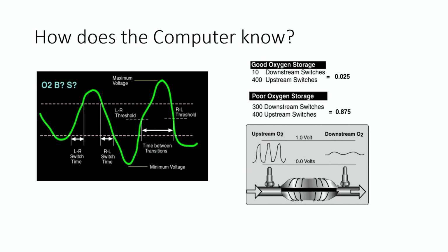But anytime we're dealing with an oxygen sensor waveform, and again, you could always go to generic OBD2 to see actual O2 sensor voltages. I know a lot of times we're dealing with lean air fuel ratio sensors now, if we were on the factory side using our scan tool. But on the screen you guys see a typical oxygen sensor waveform switching from rich to lean. Anytime we have a higher amplitude on that waveform, that's representing it's reading a rich condition in the exhaust. Anytime we have a lower part of that amplitude, that's representing a leaner exhaust.